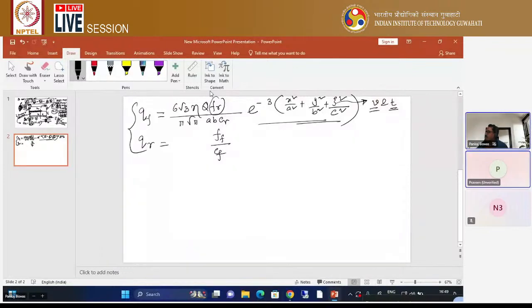So with this velocity and time t, how the moving heat source is moving, related to that I am writing a little bit here. Zeta generally you can write as z plus v into (tau minus t). Can you recall these things? I have already discussed these things. Here tau is called the moving coordinate along the z direction or moving direction. This is generally the moving coordinate, and this z is generally the fixed coordinate system.